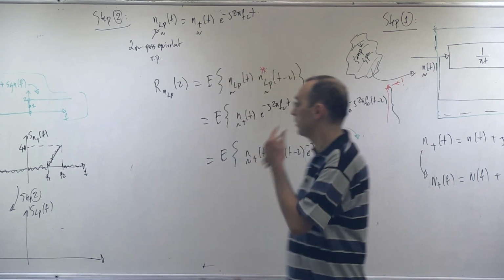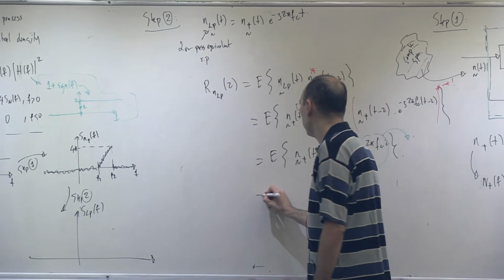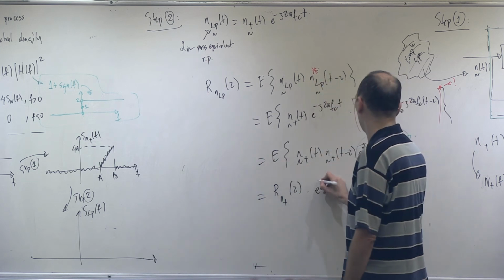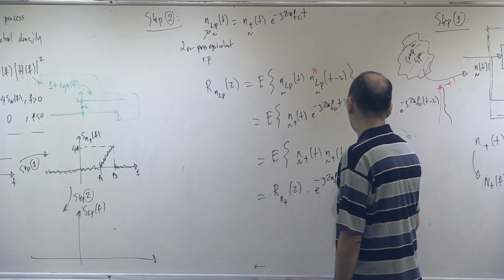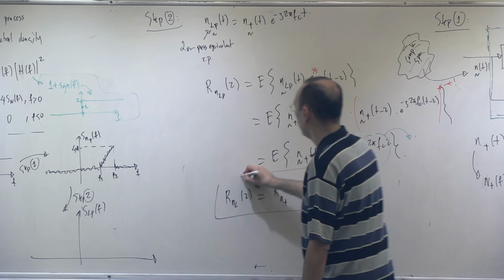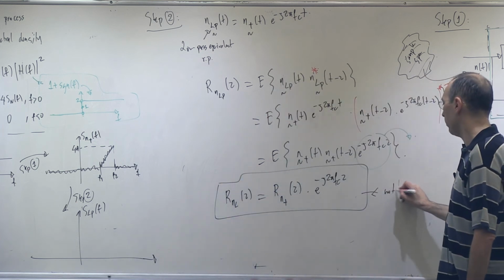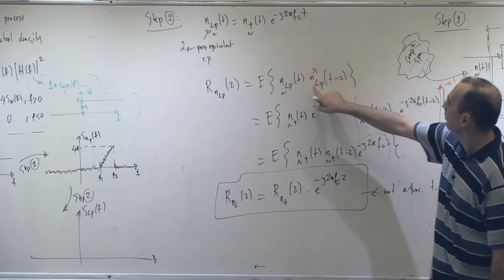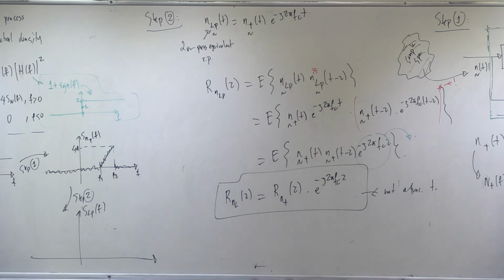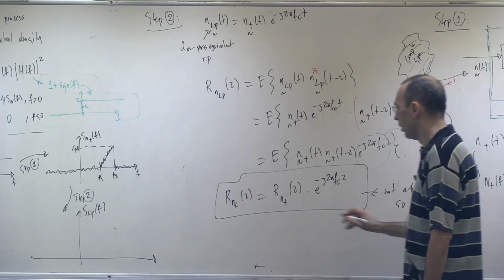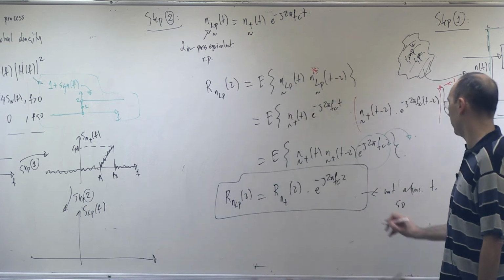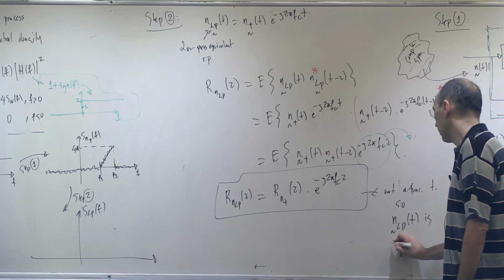Well, its power spectral density is this. Then I have the following. R n plus of tau, this part, times e to the minus j 2 pi fc tau. So everything goes very right, as you see. So do you see a t dependence over here, a function of time? So initially there were t's over here, but they got cancelled at this step. Okay, so not a function of time. So this lowpass equivalent process after step number 2 is wide sense stationary.